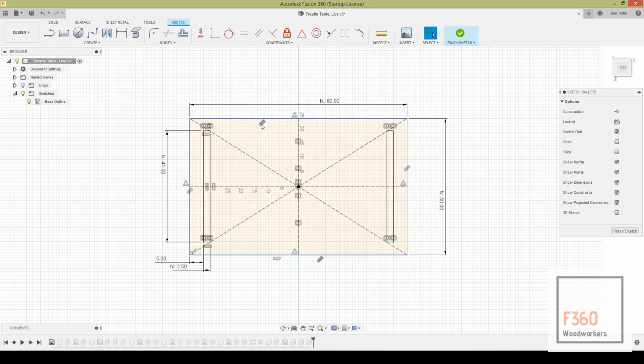Okay, so I have all of these icons right here. This is a midpoint sketch constraint. This is a parallel sketch constraint. These are symmetry sketch constraints right here. These are horizontal and vertical sketch constraints, and so on. So what I've done here is I've turned this rectangle, that normally, as soon as I would sketch it, would be blue, I've changed it all to black lines, which means my sketch is fully constrained, which also means my model will update like I've told it to.